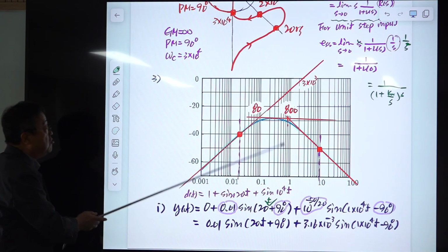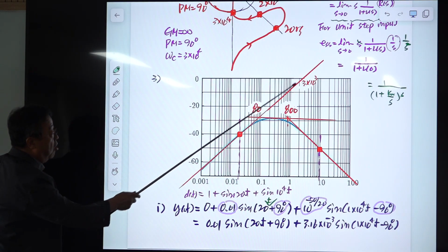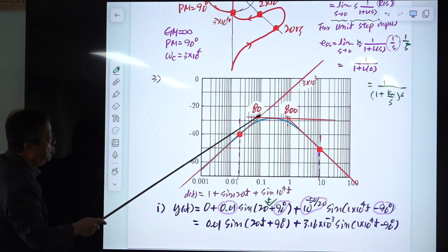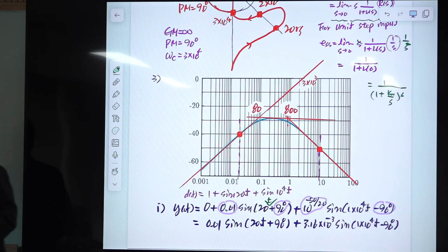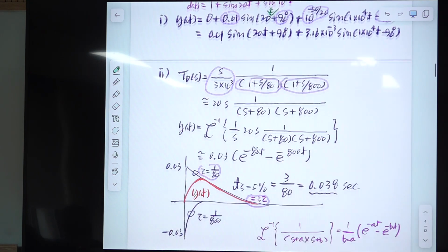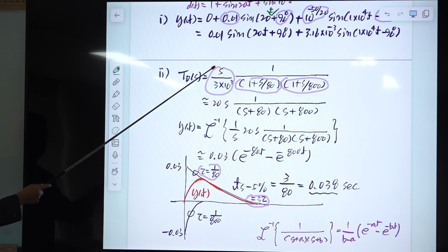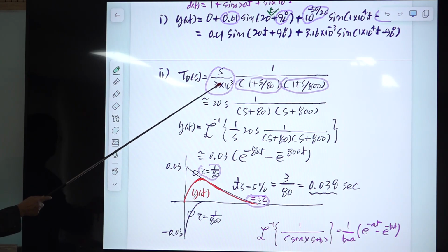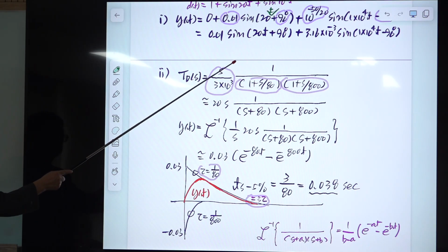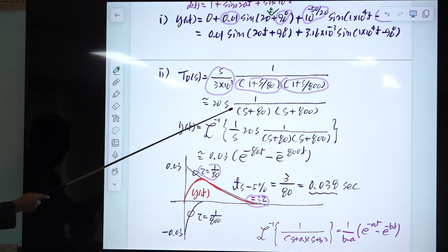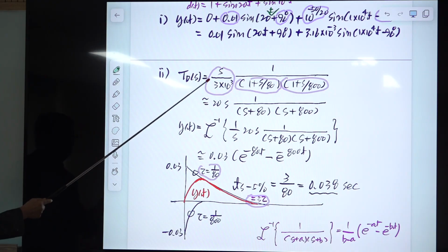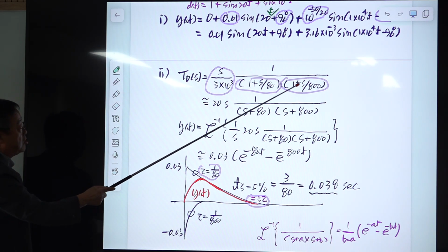With this, you have an integration gain of this one, and you have a pole. This is a second order system. So this is integration, and the integration gain comes here, because when you put this number here, that becomes 1. 1 is the 0 dB line. So this is the integration gain and one pole and another pole.